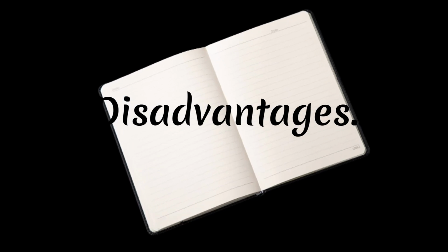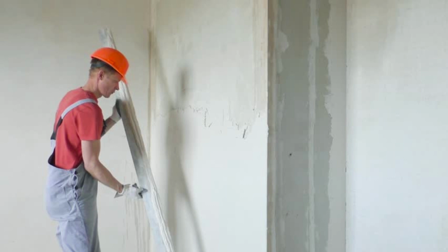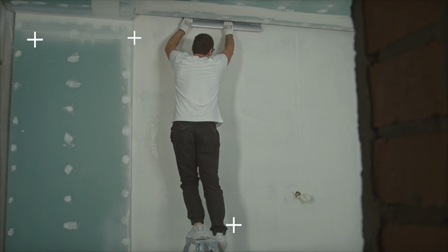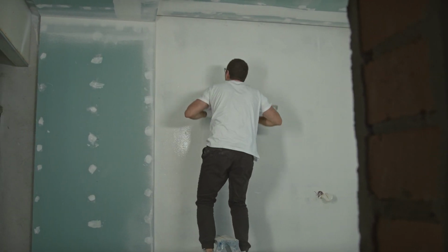Every material has a few disadvantages as well. The main disadvantage of the gypsum plaster is it cannot be used for outer walls since they retain dampness. It is not highly moisture resistant. It is not suitable for the areas that are exposed to moisture such as bathroom, kitchen, toilet and wash areas. Gypsum plaster is not recommended to use in the area subjected to high moisture condition.